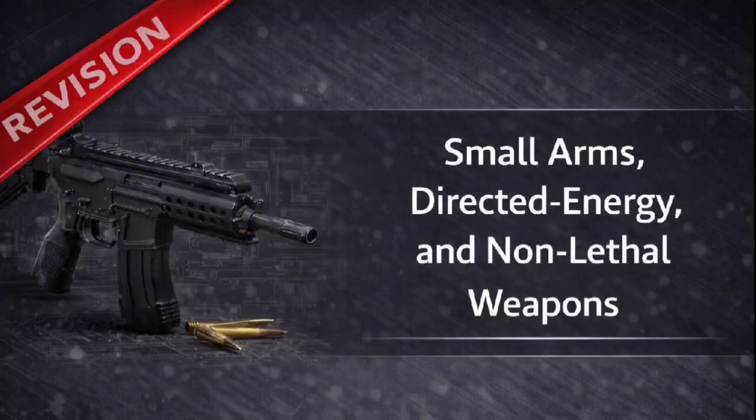And the final gas system is the lightest, but also the dirtiest. Direct gas action. Direct gas action eliminates the piston entirely. The gas just travels through a tube and blows directly onto the bolt carrier assembly itself. Which must make it very lightweight. It creates the lightest possible moving mass, but it has a very serious drawback. It deposits corrosive carbon residue and fouling directly into the sensitive mechanism and receiver. This leads to higher maintenance and a greater potential for stoppages.